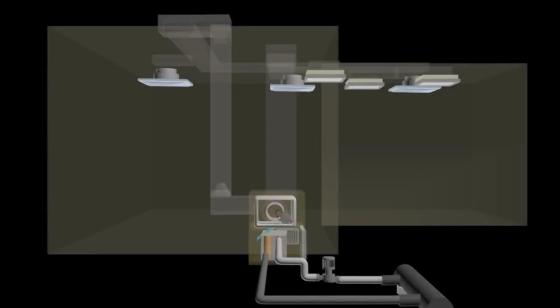For the airflow system, it is operated using an auxiliary fan which creates the air cycle from the room and mixes it with fresh air from the outside into the air handling unit and returns it back to the room. The type of fan used is a centrifugal fan, powered by a motor and connected through a belting.